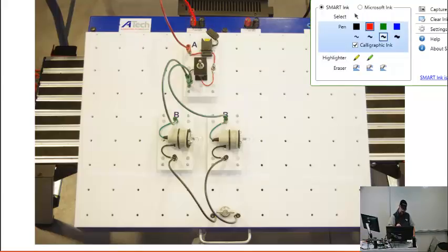I'm going to trace this wire. So I have power going to this. It comes up. It goes through my fuse. Goes through my switch to these 2 wires. Oh, okay, so now I have 2 wires going out. So if I have 12 volts right there, and I can put a meter there and figure that out, I'm going to follow this. I'm going to say, okay, there's 12 volts. And I want to verify that. I want to put my meter there and find that out. Or my power probe, and you guys will figure out what a power probe is shortly. So now I've got 12 volts there, 12 volts there. Okay.